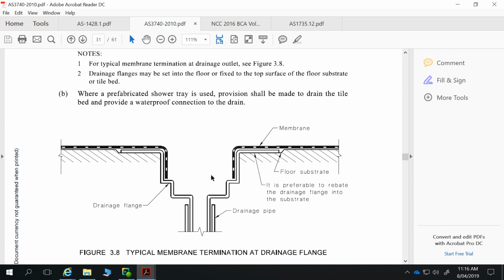So for every 80 millimeters of travel in your bathroom floor, you're dropping down 1 millimeter. So for every 800 millimeters in your bathroom, you drop down 10 millimeters already. We want to limit our set downs in our concrete slabs to 50 millimeters. If we go beyond that set down of 50 millimeters, then we're starting to do drastic things with our slabs to achieve those set downs. So we want to minimize that.